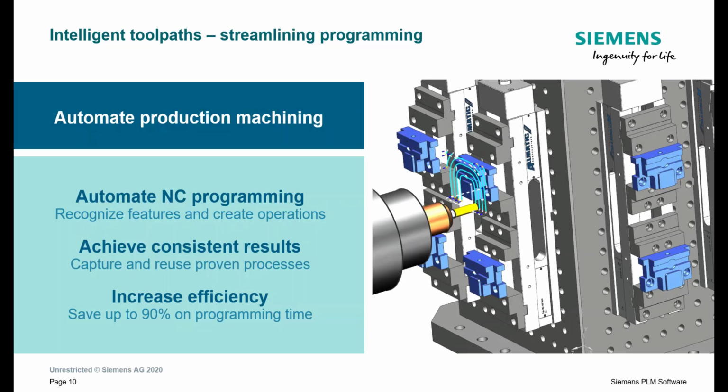With the volume-based milling in NX, the programming process is automated and associative. You select the 3D model faces that need to be machined, and the system calculates the machining volume and generates the toolpaths to remove the material. If the design changes, the toolpaths update automatically. Multiple parts programming enables faster programming of setups with multiple parts. It can save you a lot of time on programming a large number of parts.